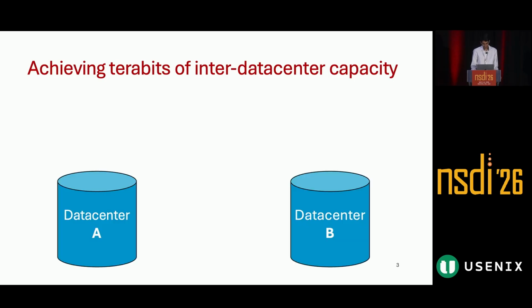First, we have our data centers, and they're connected by an optical link, which consists of a wavelength at a particular modulation format and at a particular region of the electromagnetic spectrum. In this case, it's at 1547 nanometers, and the modulation format is 8 QAM, which means that it can support 3 bits per symbol of the light wave.